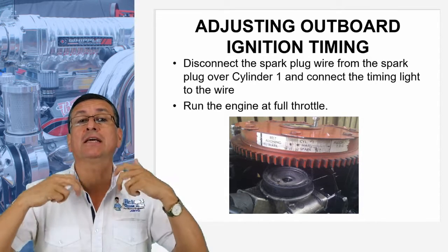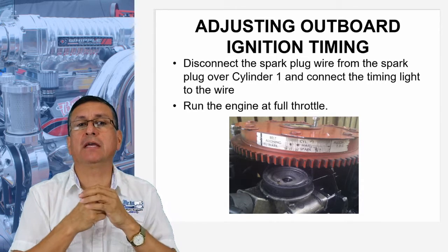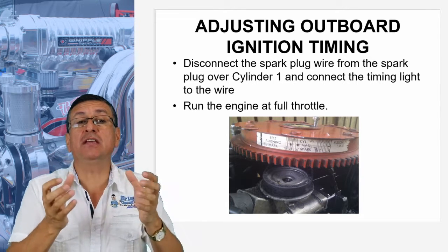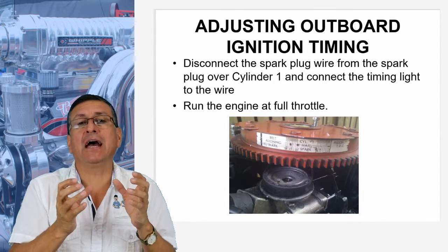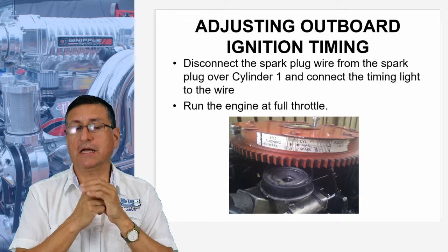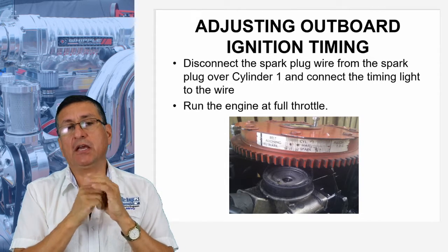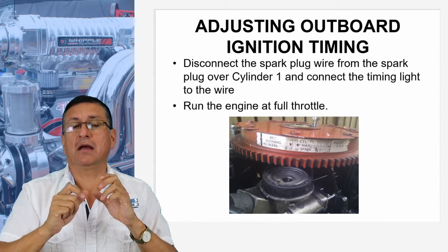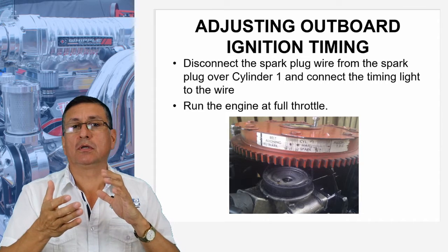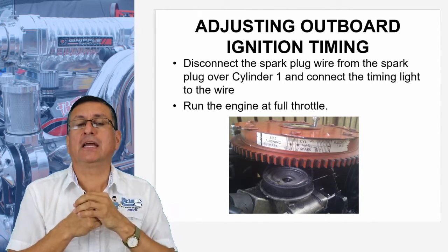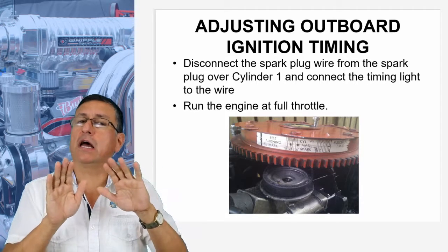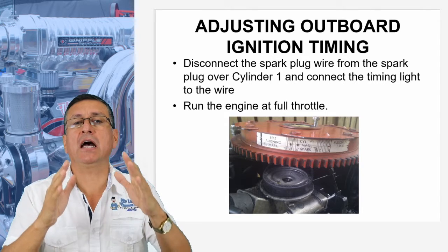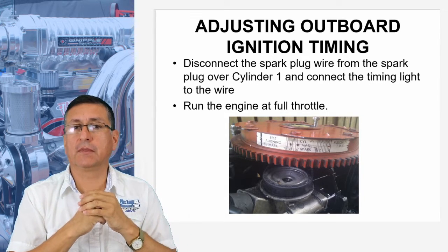But when the engine accelerates, when the RPMs increase and the load increases, the engine itself adjusts the timing, advance or retard. I never mentioned that before because that calibration of the timing according with the RPM and the load when the engine is running creates confusion. For that reason, I only explained the procedure to do the timing adjustment calibration in idle.